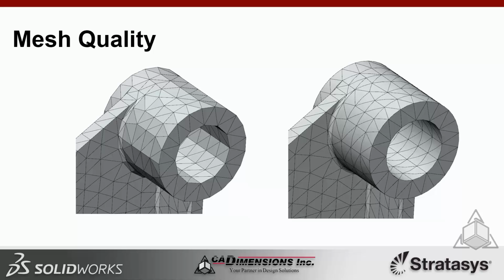So what I typically do is my first run or two possibly are with draft quality elements. I don't really worry about mesh refinement all that much. I just want to make sure all my inputs are good, and then I move to high quality elements.